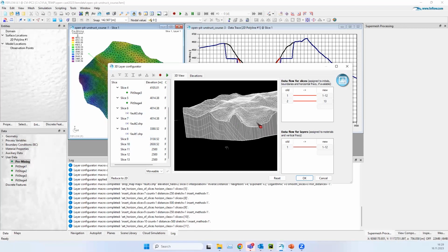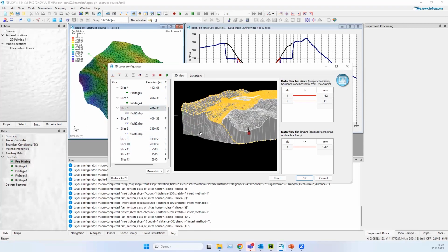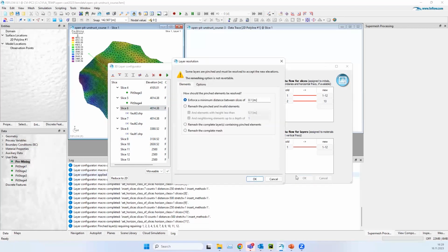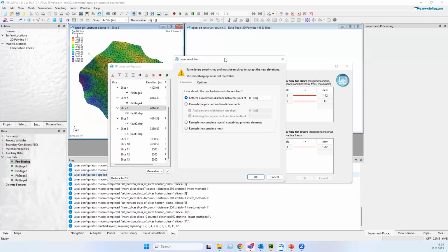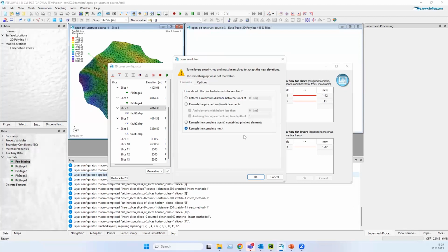So we add some folds here, and we also have some vertical layers with some continuous thickness. If we press OK, this will be the first experience with the 3D structure meshes in FEFLOW. Maybe it happens to you in situations where you didn't expect, because the elevation was touching different surfaces, and now FEFLOW is going to ask. Here we are going to say that we want to take the entire model domain and create a full structure mesh.